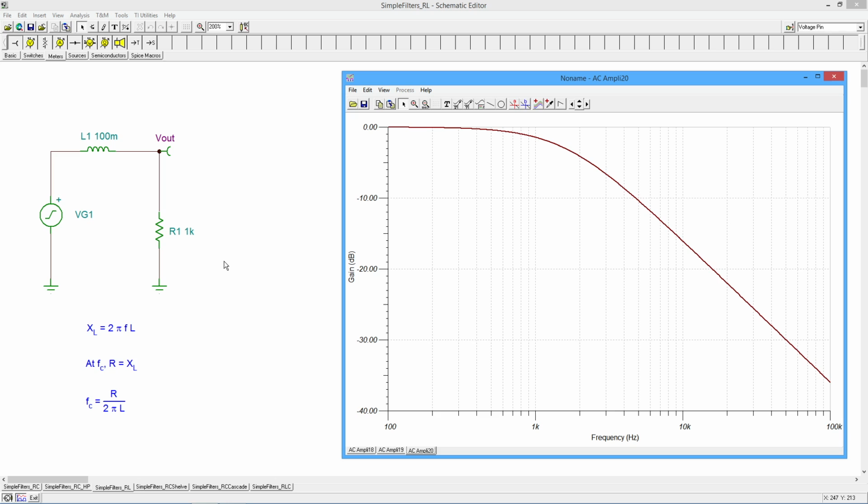If you want to look at a little bit more complicated kind of a response, we're going to have to perhaps use inductors or go to an active circuit using transistors or op amps to do something a little bit more complicated in terms of the response out here. But, for what we're looking at here, simple cap resistor combination will work fine.